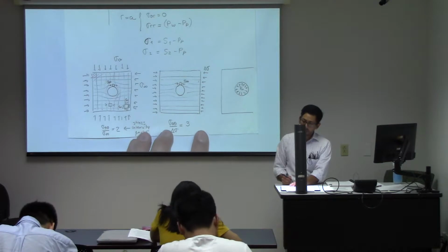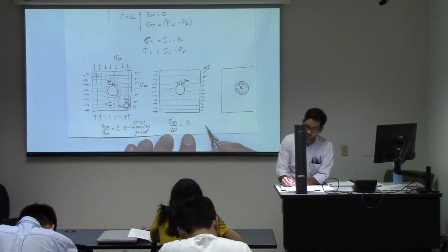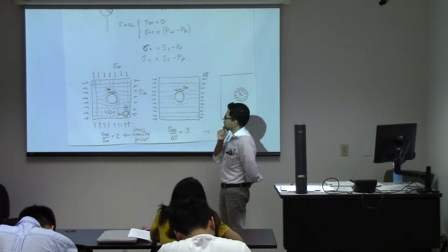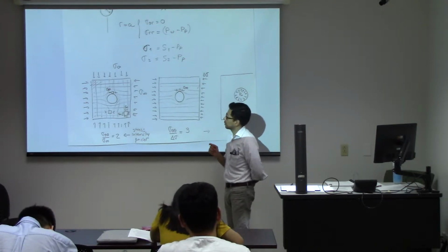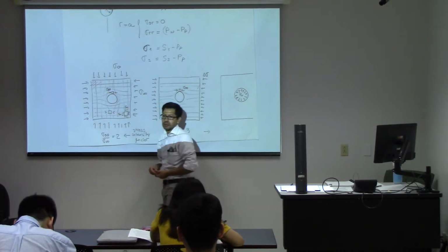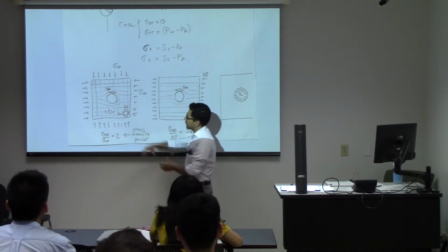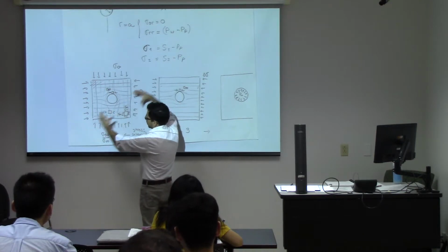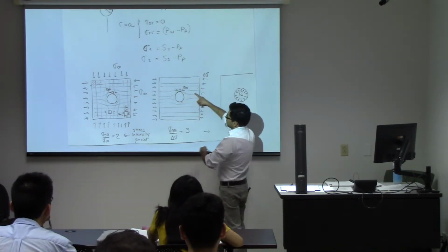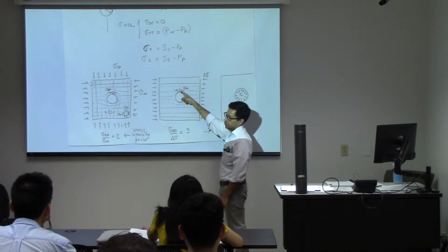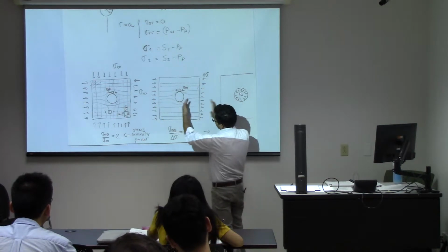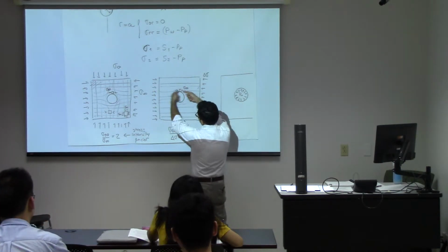we're also going to have some stress intensity factor. But before I go to that, probably I was assuming something that was not very obvious. Is this hoop stress compression or tension? It is compression because I'm compressing everything. So this one is compression. What about here? Is this hoop stress at this position compression or tension? It's compression because, again, I'm compressing all of this, and these are lines of compression.